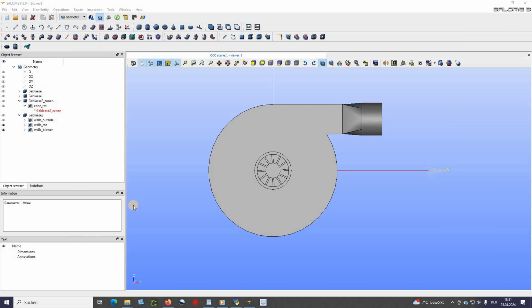For this simulation, I am aiming for a coarse mesh with a total cell number between 2 and 4 million cells. The coarser the mesh, the larger the time step. This means you can calculate the time of 5 seconds relatively quickly with my powerful PC.